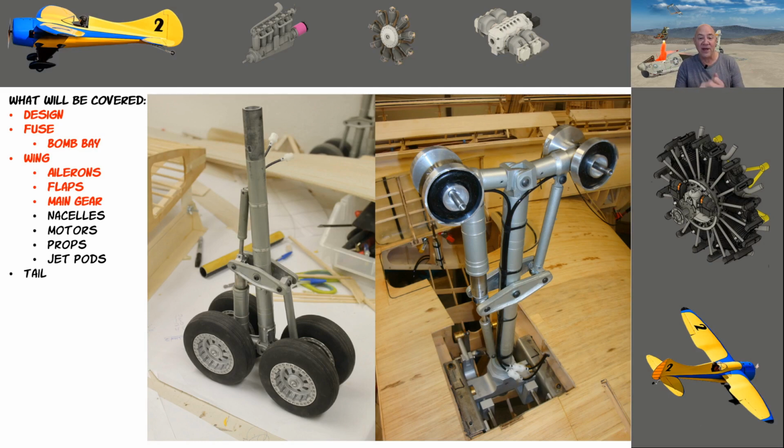And then when they finally built the landing gear, they came in twice the weight they were supposed to be. It took up twice the volume in the wing where the pivot mechanism is, and I just had to start all over. I had to redesign the entire center section of my wing. And since I did that, I redesigned the outside to make sure that the spars were just a little bit beefier. So when you're looking at that gear on the left there, the only thing that came from them is the pivot arm and basically the strut. Everything else in there I made out of carbon fiber.